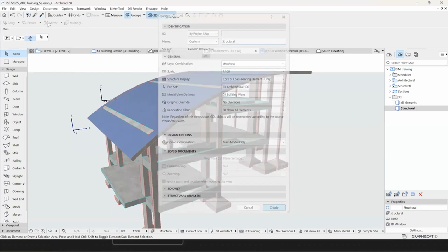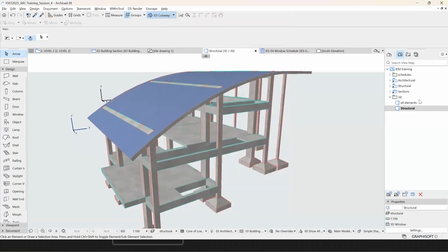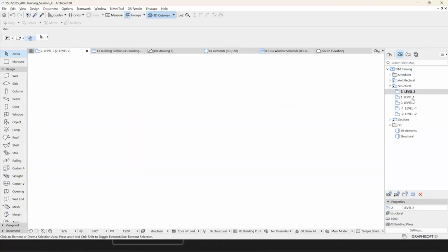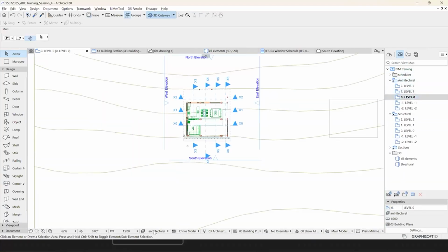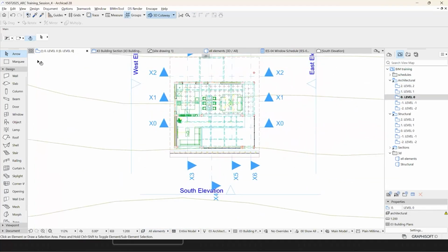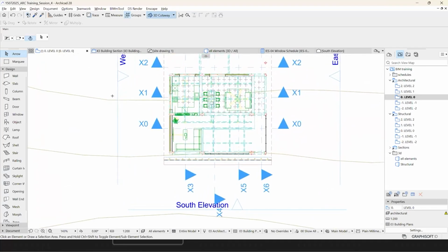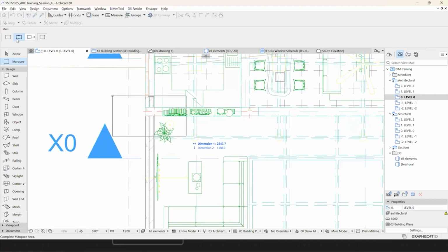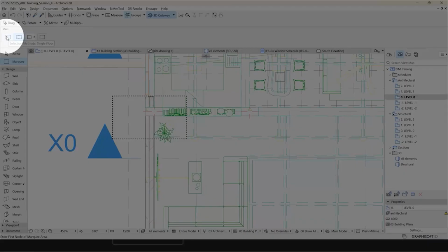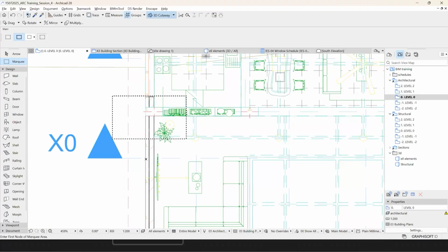So we have three 3Ds. Sometimes what we do is when we have the whole element and we want to focus on certain parts, we can also do that. I hope I have taken that during the session. Otherwise, I'll just do that again. Let's say I want to take a detail of the specific area. So you can use the marquee tool here, a box, like this. I'm using the all floor option here. There are two options mainly. One is the single floor and all floor. I want all floor so that top to bottom I get the whole detail.